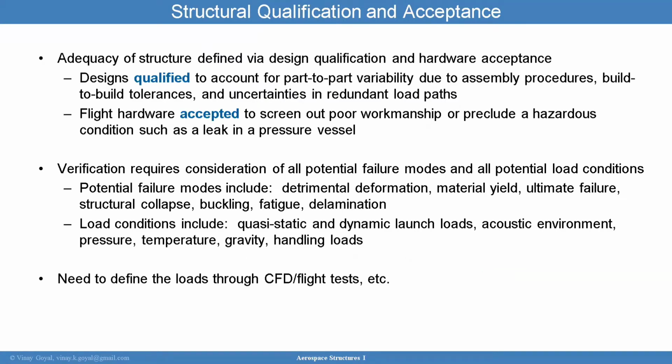So for me to step into a structural qualification test program, I want to make sure first that I have the loads very well defined. And the structural qualification is important. The structural qualification is the test. It's a test article of the same kind as the one you're going to fly.